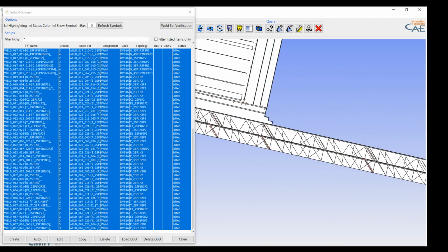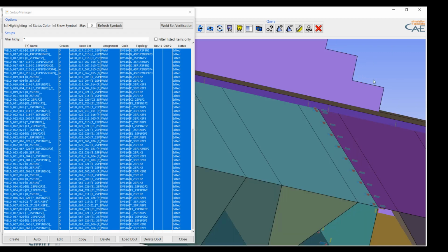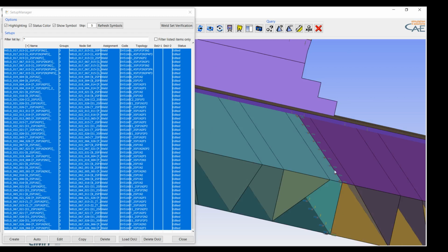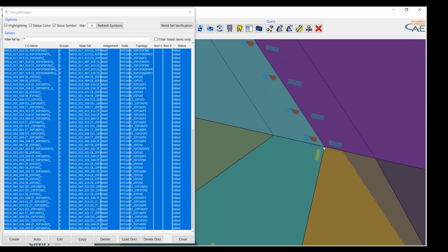And maybe let's take a look here. Again, this is a profile set, as you can see here. We have the profile here, and here is another profile. So the attached sheet is this horizontal sheet. Here we have a full penetration weld, and we have base material here on the inside, and the weld cross section will be checked here for the blue element.